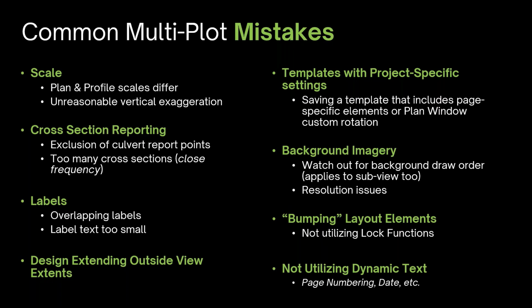And then the final common multi-plot mistake that we'll talk about or show you how to use today is dynamic text. So there are some fields within a text rectangle where you can have dynamic text, such as a page number or the date or even your design file. And we're going to show you how to leverage that within your multi-plot.